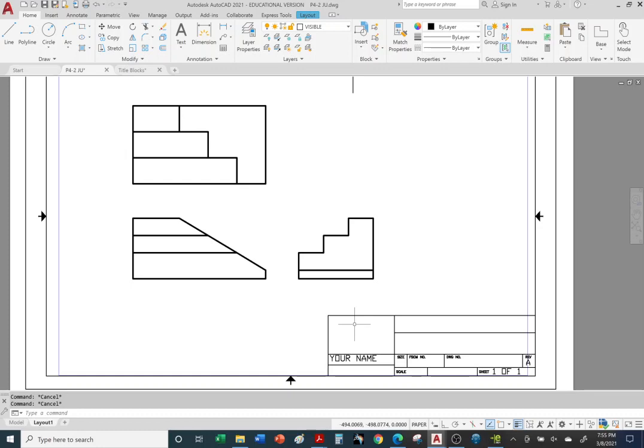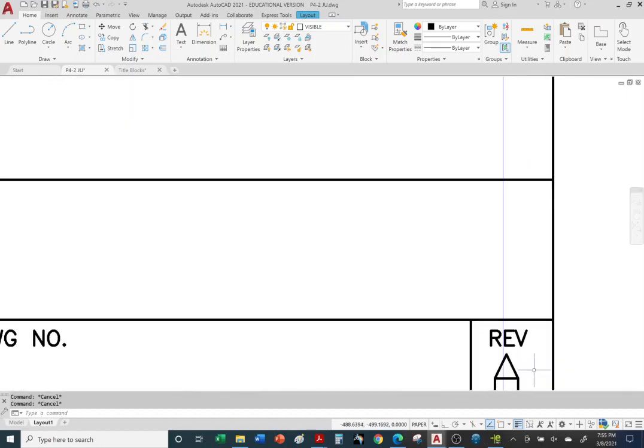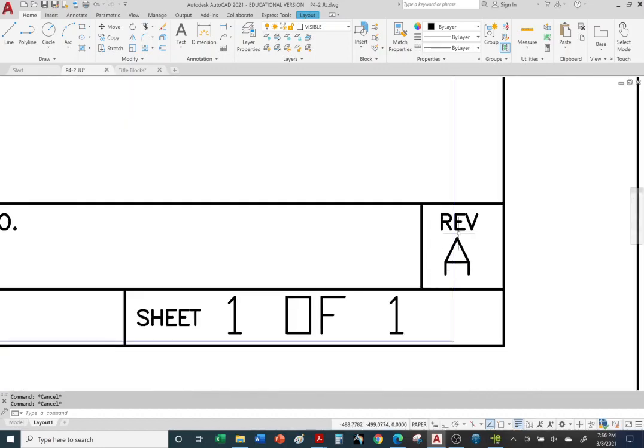You got to stop the machine shop and call them and say, hey, you know what? We need to make a change. Have you guys started machining? Like, no, we haven't started machining yet. Okay, we're going to send you a new drawing. The part is taller. So now you have to change the revision to a B. You just go down the alphabet, right? Avoid using letters like O, I, L, because they can be confused for numbers or other letters. So we do avoid using some of the letters in the alphabet.